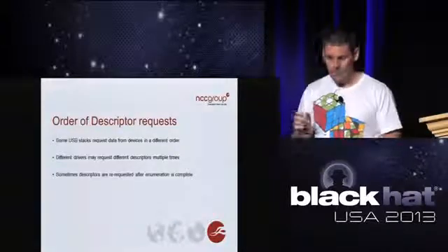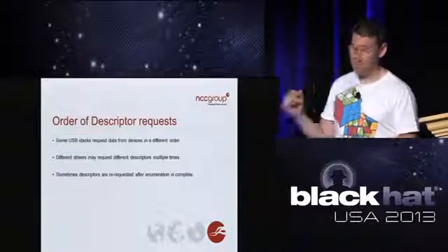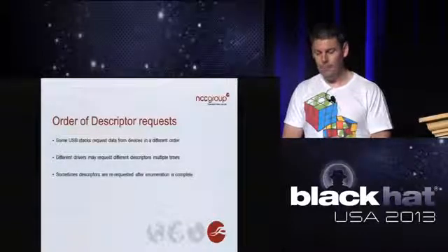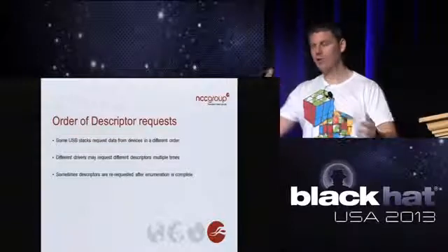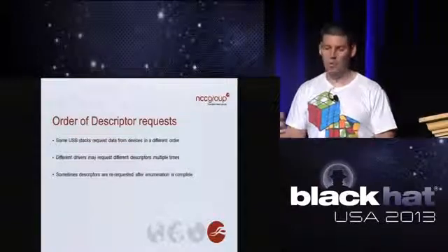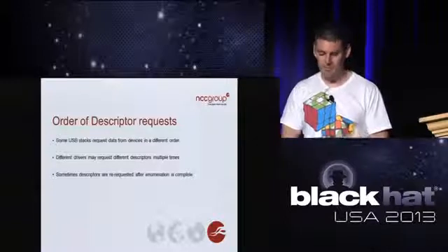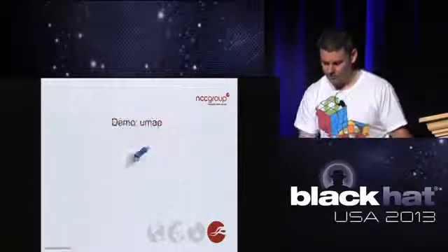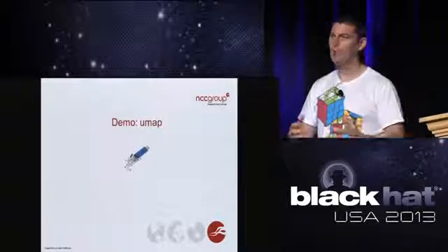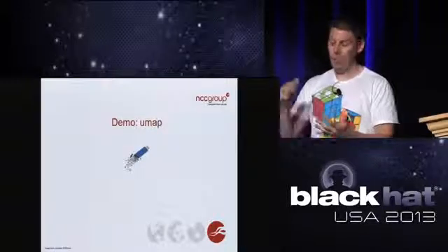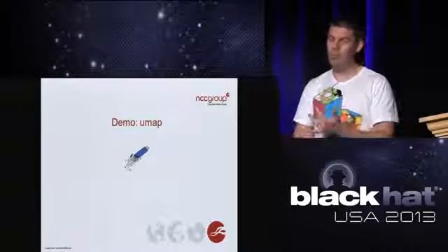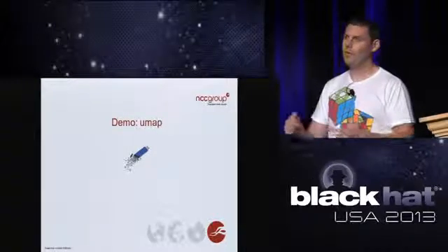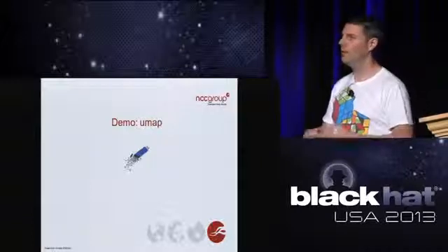So some USB stacks request that data in different order. You might get additional descriptors that are requested multiple times by different layers of the stack. So all in all, there's plenty of information that you can gain that will help you identify A, what the operating system is running on the device, and B, what device drivers are installed that you could then query and potentially fuzz.